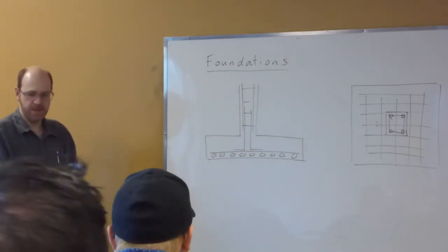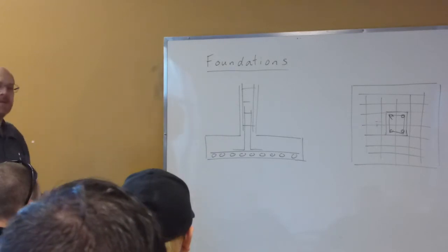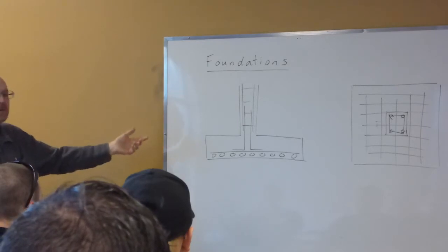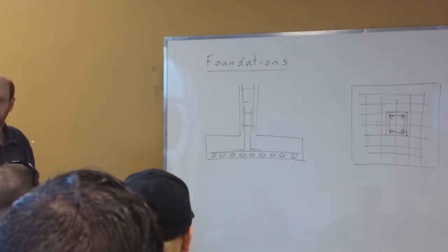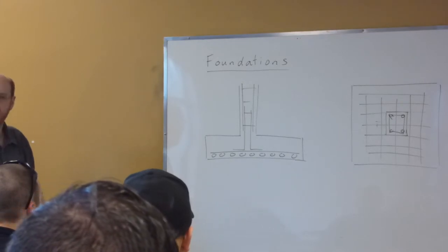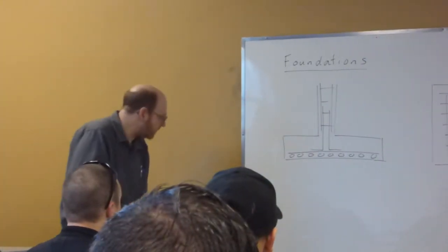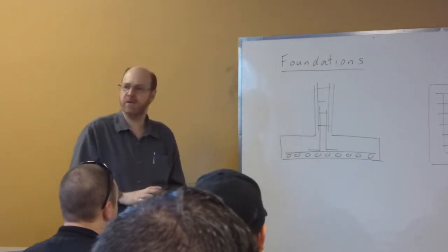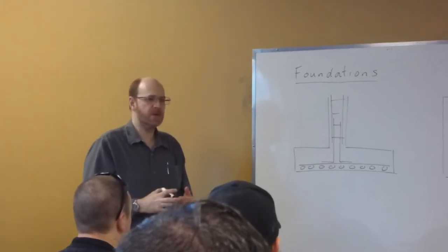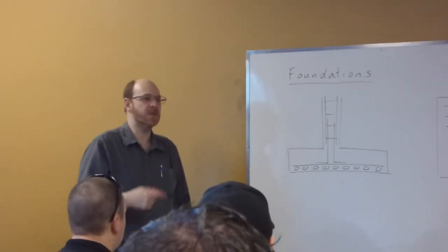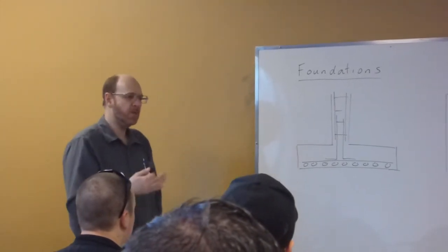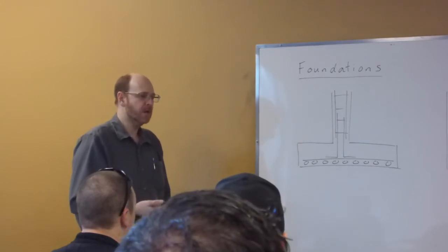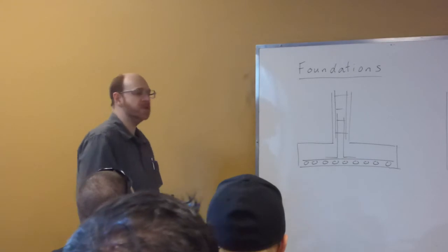Now there's a few minor little things. It's designed much like a slab in the sense that we want to position our, or size our footing so that we don't require any stirrups. Stirrups are rare in footings. So if you remember with our slab design, what we had was a shear calculation for figuring out our depth. Right? We started with an estimate of our depth based on what was necessary to avoid deflection calculations. And then we went and checked to see whether or not it could handle the shear. And if necessary at that stage, we make the slab thicker so that we don't have to put in shear reinforcement. So we do much the same sort of thing here.